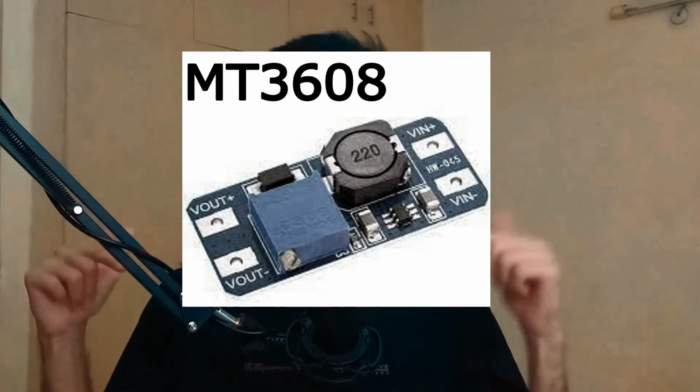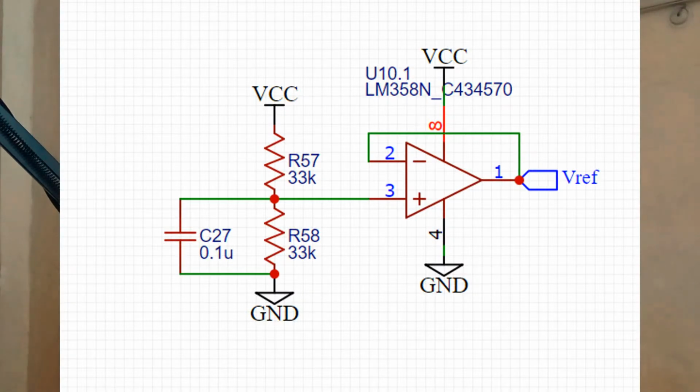Take 5 volts from the USB port through a DC barrel jack because, well, micro USB ports are kind of crap. Boost that voltage to about 9 volts using a standard boost converter module. I don't remember the number, I'll put it right in front. And to turn it into a kind of bipolar supply, I planned to generate a mid-rail reference voltage using a resistor voltage divider and buffer.